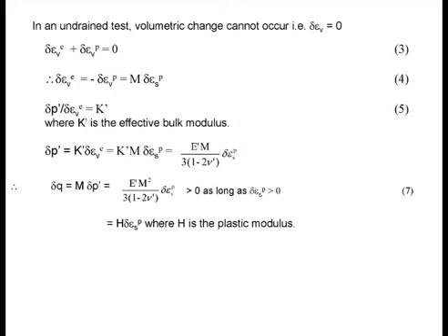Okay? So physically, the soil is trying to dilate, but the water is pulling it back in. So you develop suction. And what does that mean? Negative excess pore water pressure. So the negative excess pore water pressure is the mechanism of the soil to keep that volumetric strain the same, or at 0. You understand what I mean?